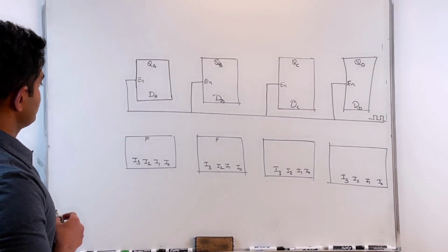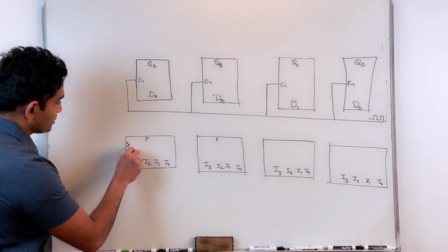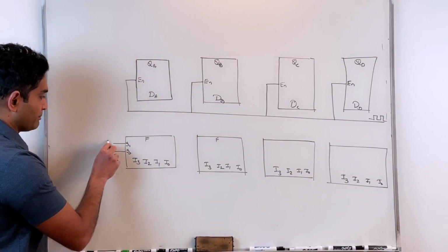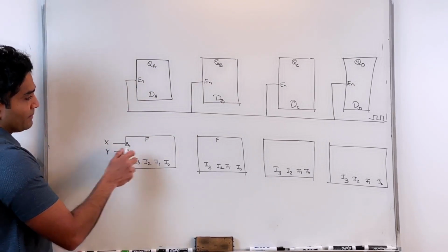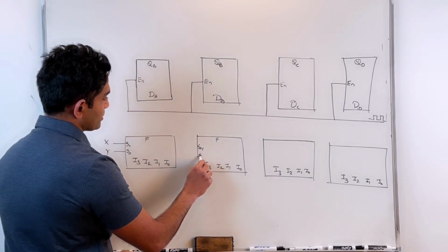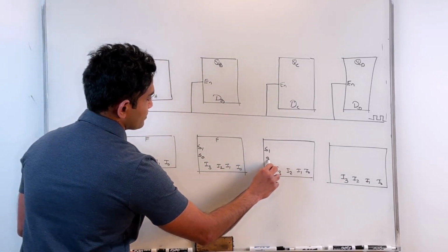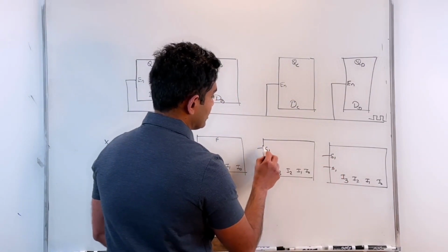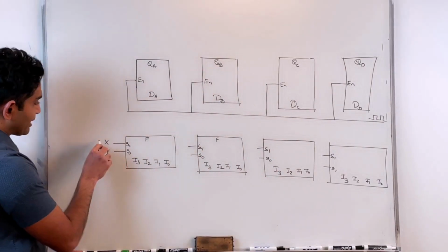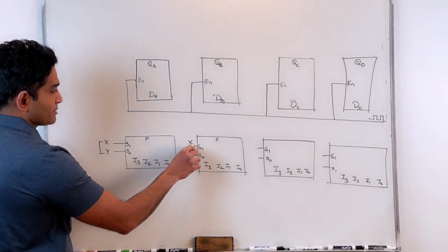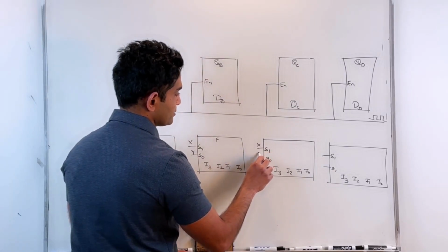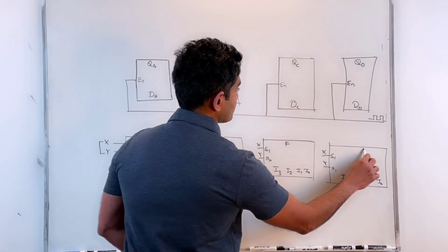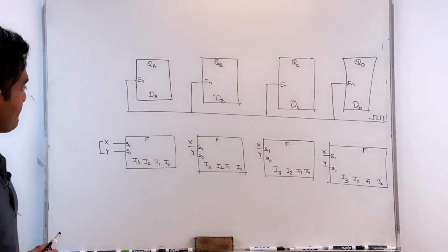These are the selector inputs S1, S0 for the multiplexer, where I'm applying my X and Y. Although I do not show these, each of my selector inputs are tied together. That means on each of my selector inputs, I'm applying the same values of X and Y. That's going to be X, Y, X, Y, X, and Y. That's the output.